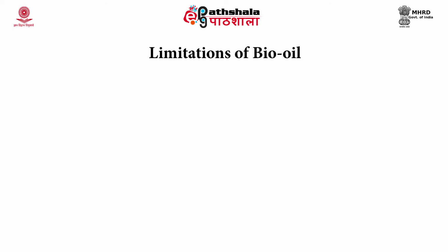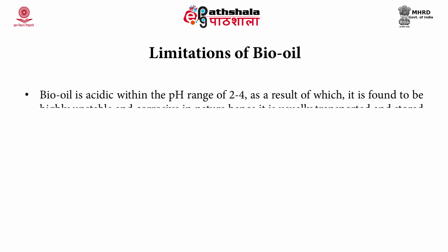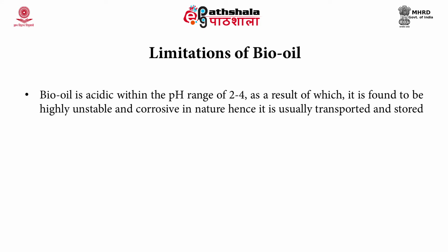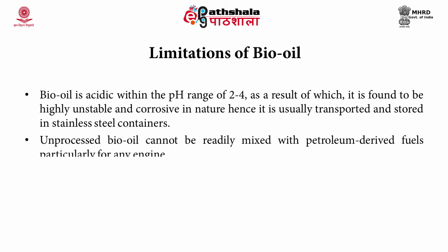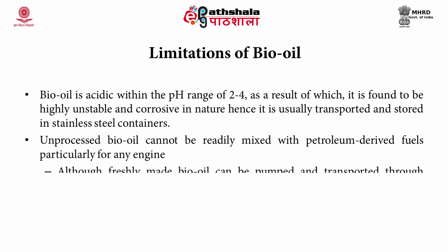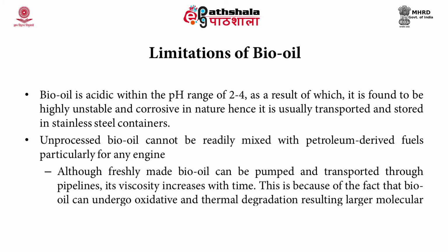But bio oil is acidic within a pH range of 2 to 4, and because of that it is highly unstable and corrosive in nature, and it is difficult in the transportation and storage. Here it should be stored in stainless steel containers because of this acidic nature of the bio oil. The freshly made bio oil can be pumped and transported through pipelines, and later on its viscosity increases, that is, viscosity increases with time.